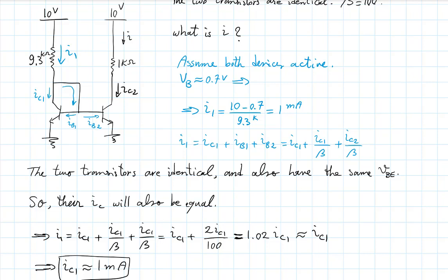Remember that model of the diode and the controlled current source on top of it? That's what this is doing. The transistor is acting as a current source whose current is determined by what you feed to its input. Now you could have fed a given value of VBE at the input, a very precisely calculated base emitter voltage, so that when you take the exponential of VBE over VT and multiply by IS, you get 1 milliamp there. But I think you would agree with me that that would not be a good design because that would be extremely sensitive to the precise VBE input.